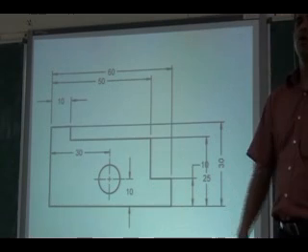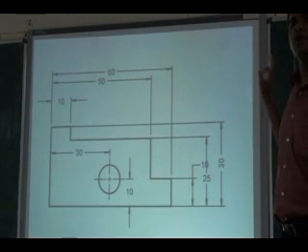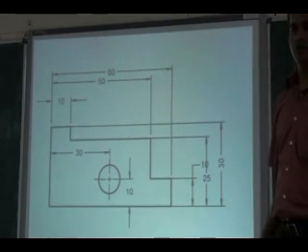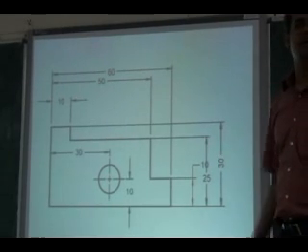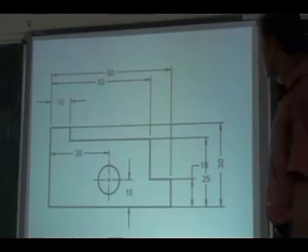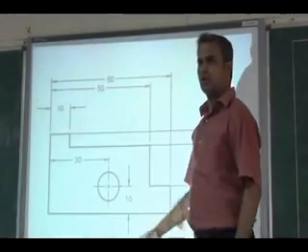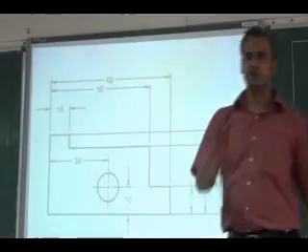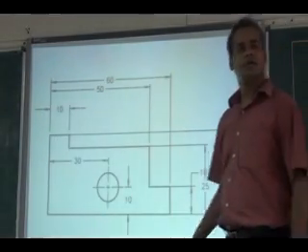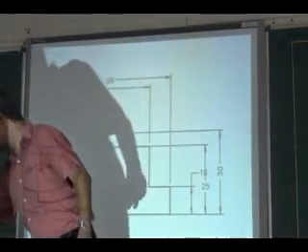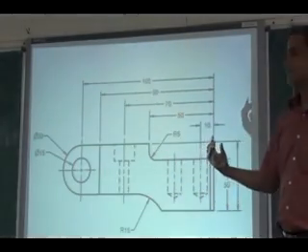As per those 3 notes, you have to place the dimension value above the line, horizontally. And this dimension you have to show outside. One more thing, in that principle you should not dimension the hidden lines. Right. You see the other drawing. Show whatever mistakes we have.